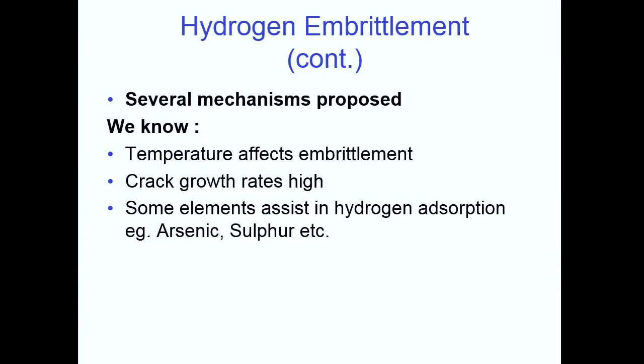Okay, so sometimes if you've had a little bit of general corrosion first of all, and you've built up an oxide layer, then the hydrogen won't go into the material. So there's definitely a surface condition effect on the adsorption.